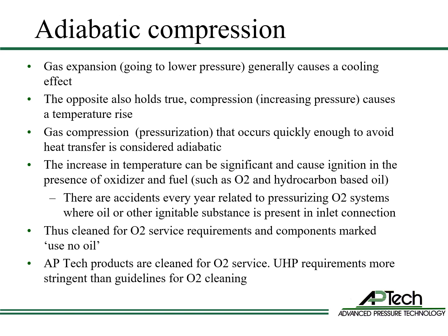As we just examined cooling effects due to gas transitioning to a lower pressure, there are also the opposite heating effects due to gas compression or increasing pressure. This is called adiabatic compression. When a gas compresses or pressurizes quickly enough to avoid heat transfer, it is considered adiabatic. The increase in temperature can be significant and cause ignition in the presence of an oxidizer and fuel.